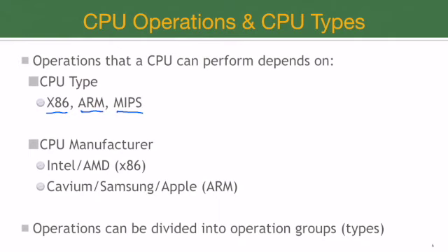So what instructions exist in a specific processor? You first need to know the type of the processor, and that will define what instructions are there in the CPU. All the x86 based processors will generally have similar kinds of instructions, and that is defined by the x86 instruction set architecture. When I am saying instructions, that also maps onto the operations. So these are the sets that are defined. Now, why do we define these sets? Why can't we make any operations and instructions, whatever we want to have in our computers?